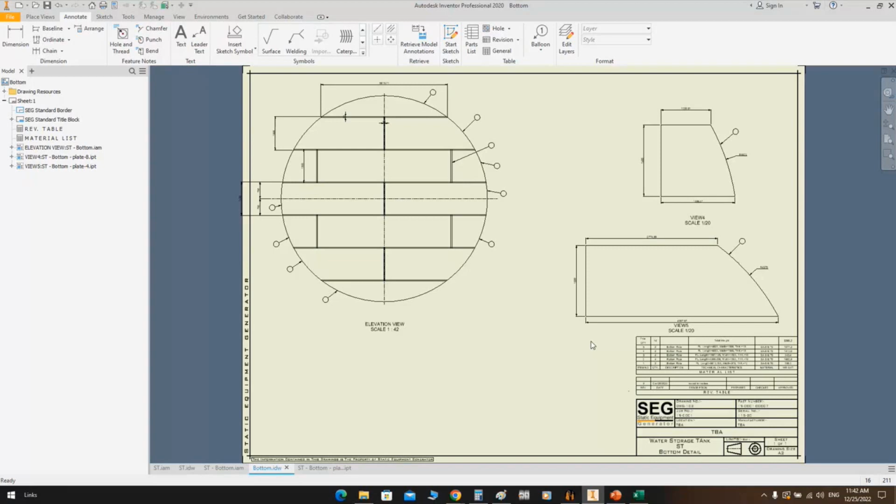In SEG software, if you have identical items, with the same description, the same technical characteristics, the same material, and the same weight, they are identical. Like flanges: if you have a 4 inch flange with a rating of 150, the same schedule, the same material, SEG will detect that they are identical and will give them the same item number.